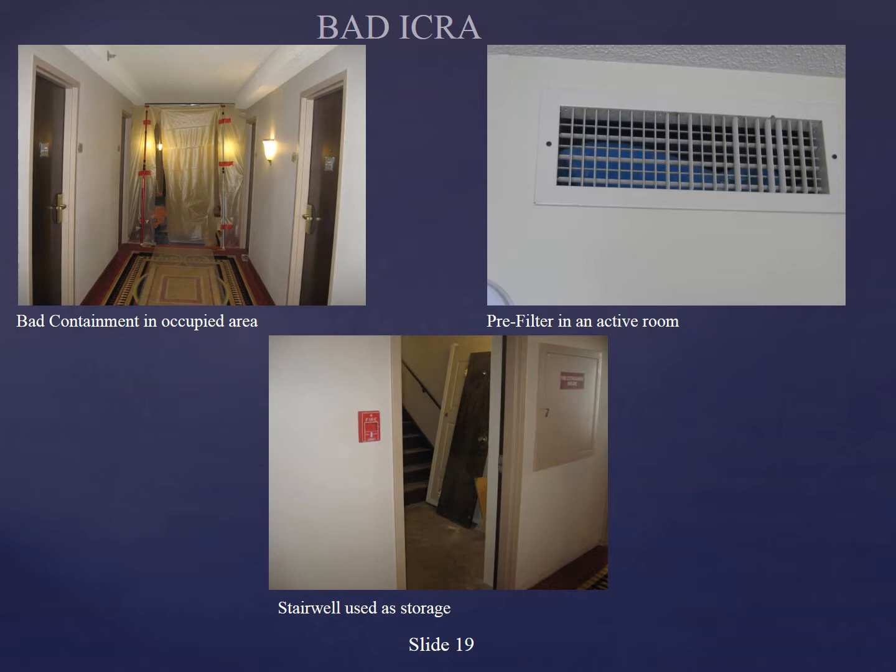I doubt this is the right rated plastic or poly for the work. Over to the right, you can see inside that vent, someone has stuck a little pre-filter, probably like an 80% filter even, into an active space as a way of trying to filter dirt and air. Again, it seems like a good idea at the time, but you can also see it's not very effectively even holding.